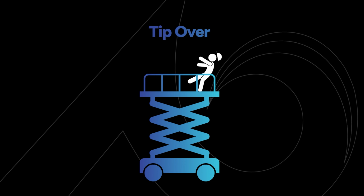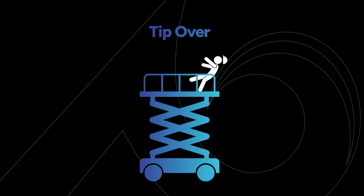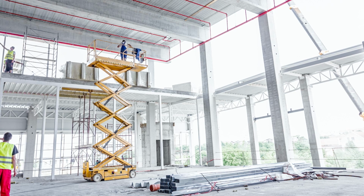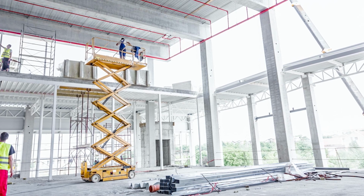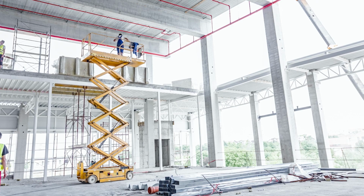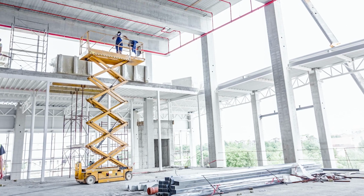Another common accident associated with scissor lifts is tip-overs due to lack of stabilization. Employers must make sure that scissor lifts are stable to prevent tip-overs or collapses before each use. To do this, manufacturers' directions for safe movement must be followed. This often prohibits the movement of the lift in an extended position. When in use, the area surrounding the scissor lift should be cleared to make sure that no other equipment on site comes in contact with the lift. Work sites need to be clear of holes, debris, slopes, or other ground obstructions that could cause the scissor lift to become unstable and tip over.